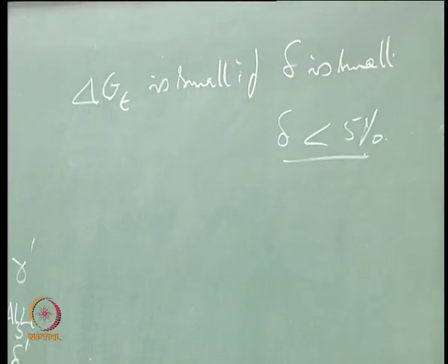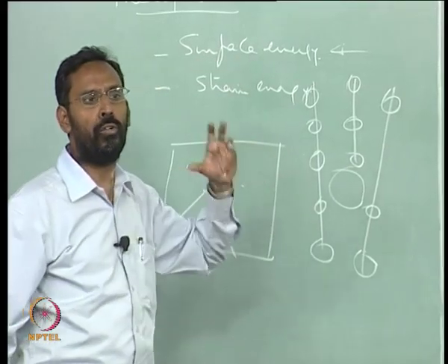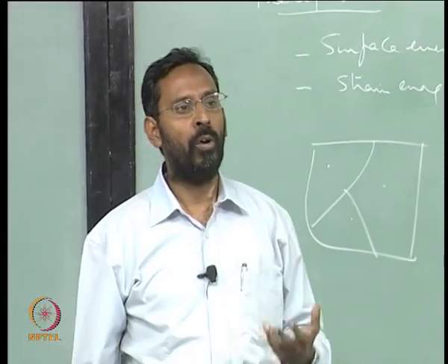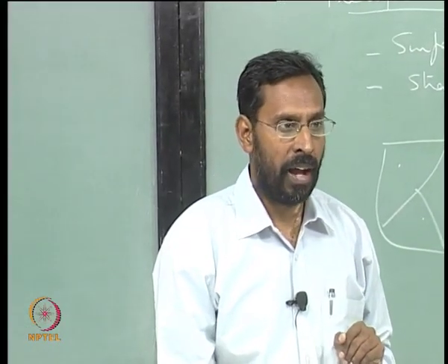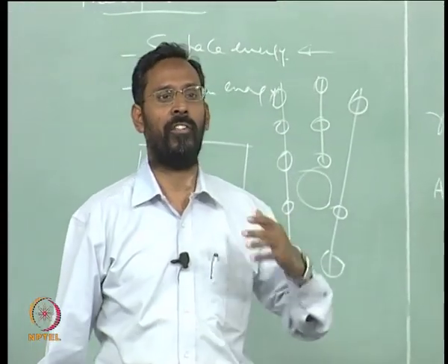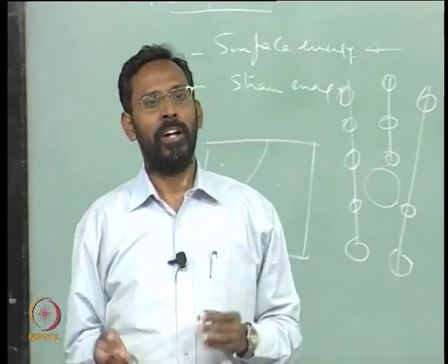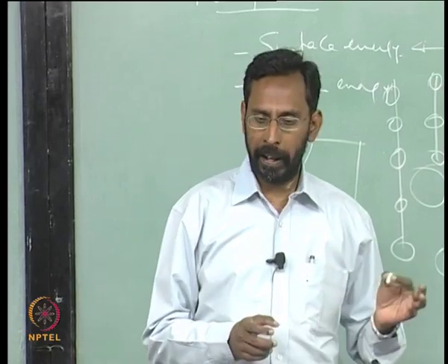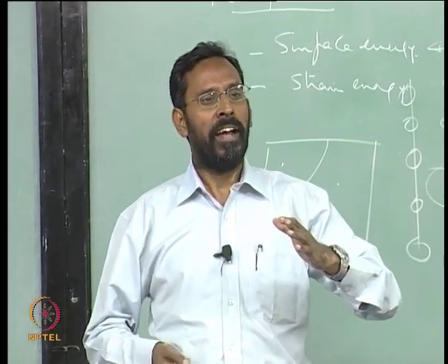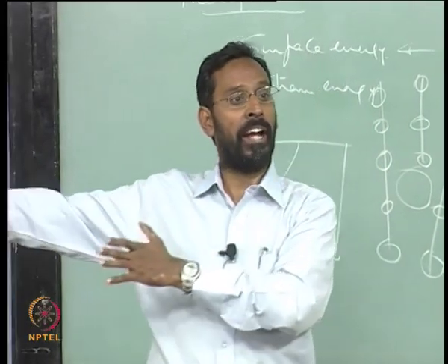Once that is the case, then what decides is the surface energy. For a given precipitate and matrix, if the strain energy is small, the system will choose that particular shape which has the lowest surface energy. And coherent interfaces, mind you, always have the lowest surface energy, because there is continuity. An analogy is a low angle grain boundary with respect to a high angle grain boundary.